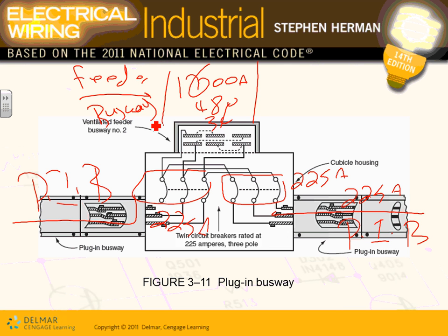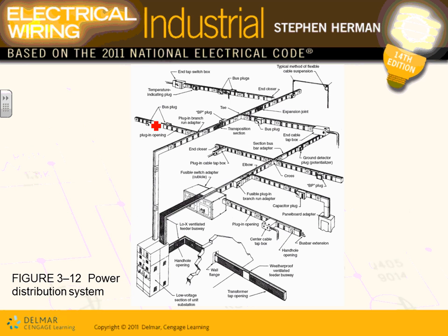You have to do exactly the same. In ours, guys, you're going to see it's 1,000 amp. Most likely it's going to be your size, 1,000 amp, and we're tapping it with 225 amps. You know what a 225 amp busway is, guys? It's exactly like a 225 amp panel. That's how much energy you can have.